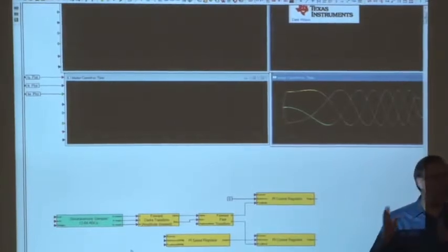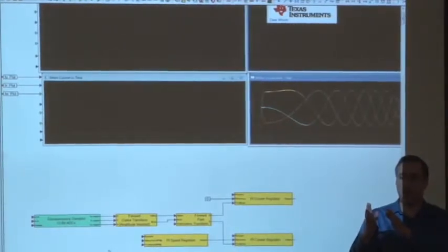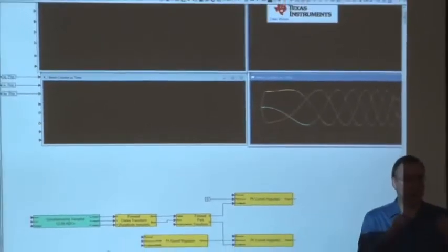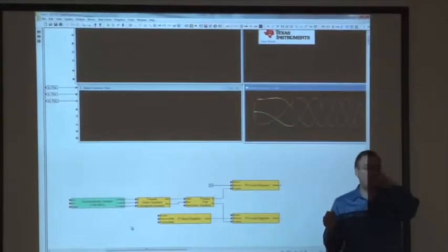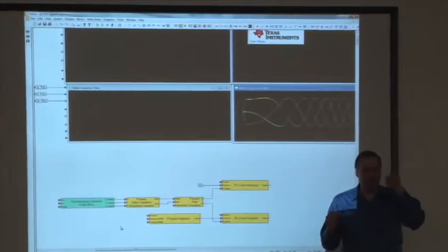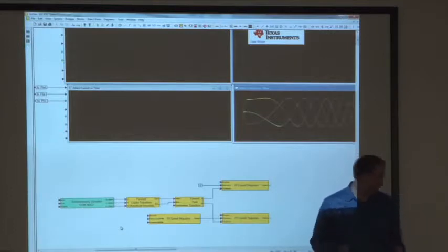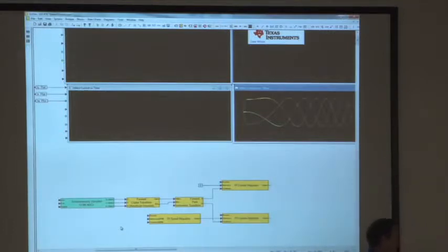field-oriented process to the PWM waveforms. We want to do these at a certain time in the PWM waveform because that's where we capture the value to be just right. In other words, the current waveform, if it's under PWM control, remember it's rippling, right? It's got ripple on it. If I capture it right in the center of that ripple, that's where I get the average value of the current. So when we put the PWM module down, we're going to create an execute signal, which we're then going to feed back to all these other blocks to say, okay, run now. All right, so we'll leave that blank for now.